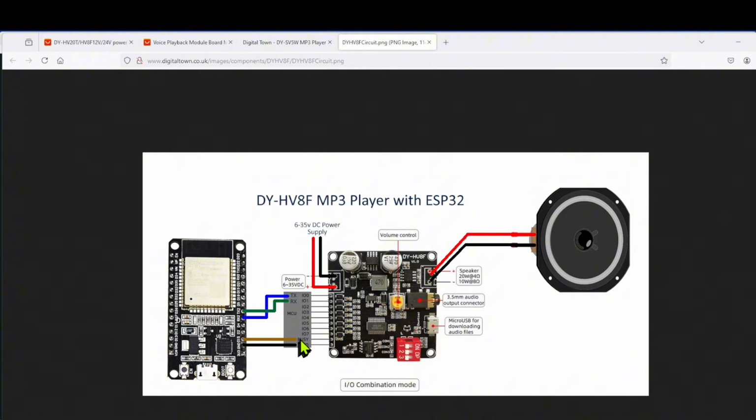So virtually the moment that the busy pin goes high, the ESP32, which is quicker than the Arduino, is going to have picked that up, and it will go, the track's ended, send the data across.